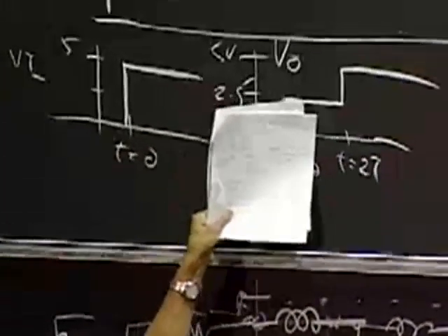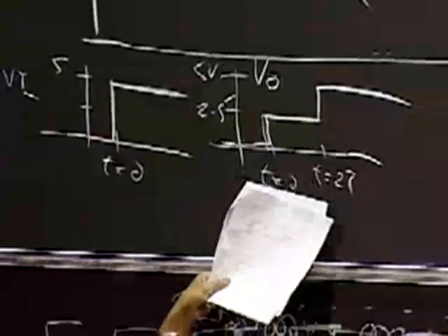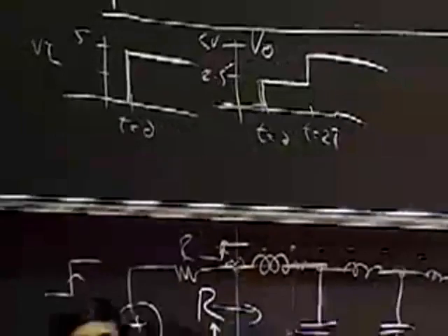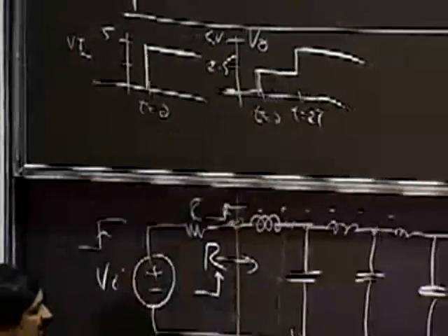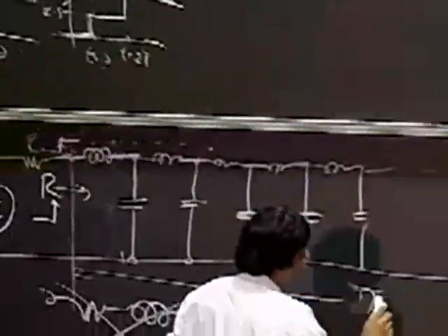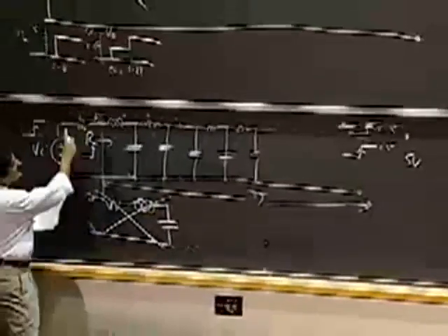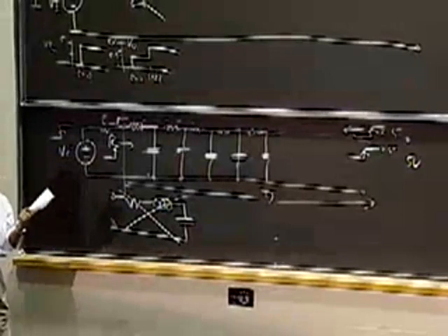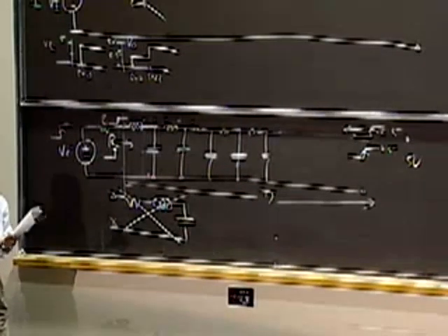So this is a wave going down, and then after a time 2t, it goes back up to 5 volts. That's a return wave. It's 2t because to get down here is t seconds, and then t seconds to come back, which is why we have 2t. That is why you see that pulse at 2.5.